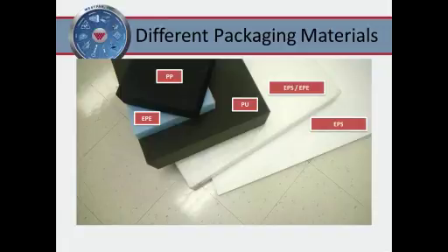Polyurethane, you're going to be in the $2 to $3 range for an equivalent volume of that. Again, depending on the materials. Sometimes they're pretty inexpensive. Sometimes they get very expensive. There are polyether urethanes and polyester urethanes, and again, depending on your particular requirement, they can range from double EPS to 4 or 5 times that. The polyethylene, the EPE expanded polyethylene, again, it depends on its density, obviously, and other factors, but it can be equal to or greater than the polyurethane pricing.